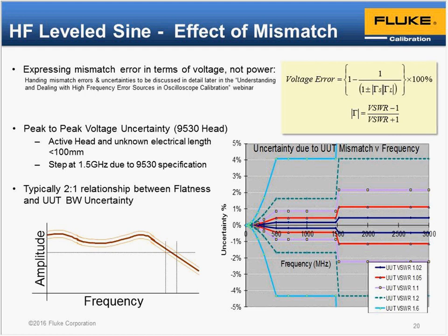In fact, I would advocate that you need to be sure what the frequency response characteristic of the scope is like, and maybe just explore a couple of frequencies either side of the nominal bandwidth frequency just to get a feel for that slope, if you do want to actually determine the uncertainty of the measurement around there and be thorough with your metrology. But this gives you an indication of the kind of coefficient, as it turns out. For those of you that are familiar with the uncertainty analysis process, that's what you're looking for.